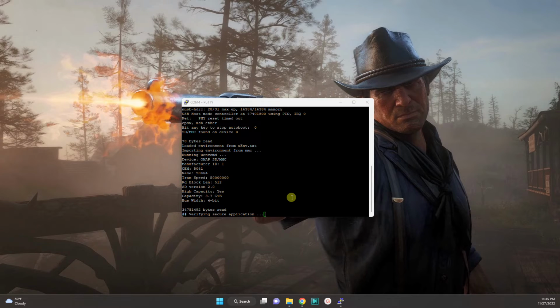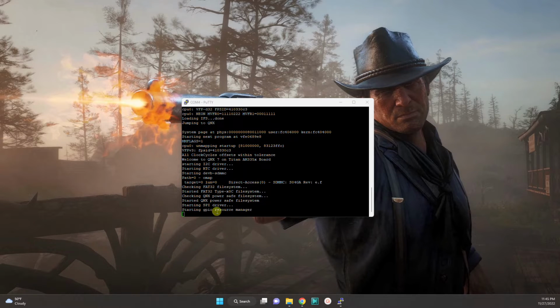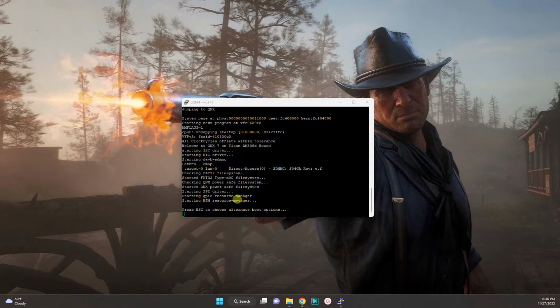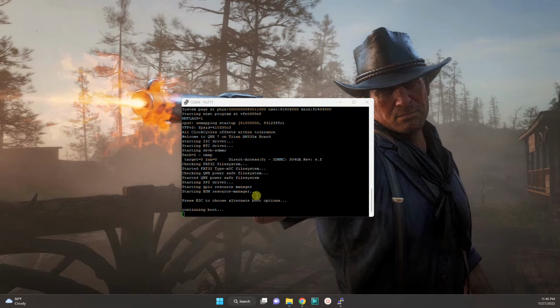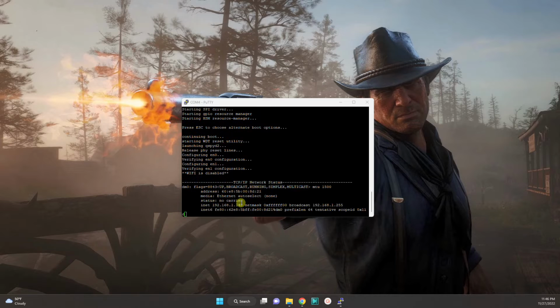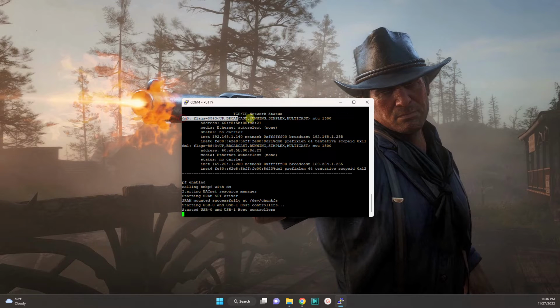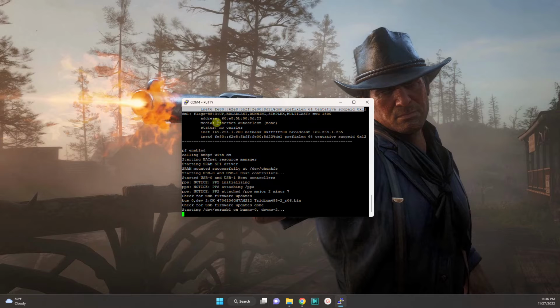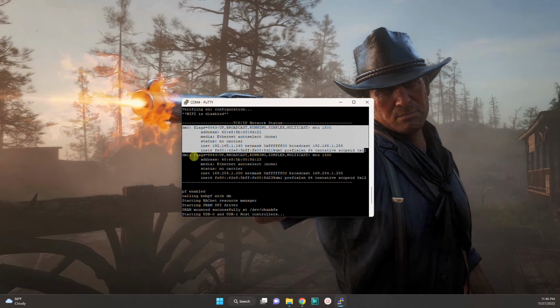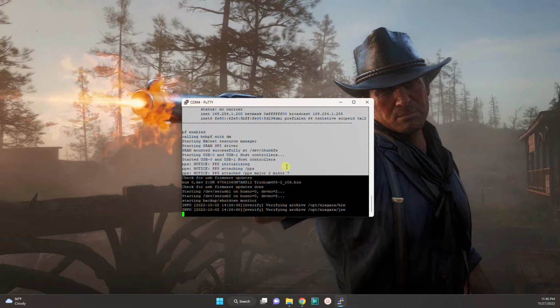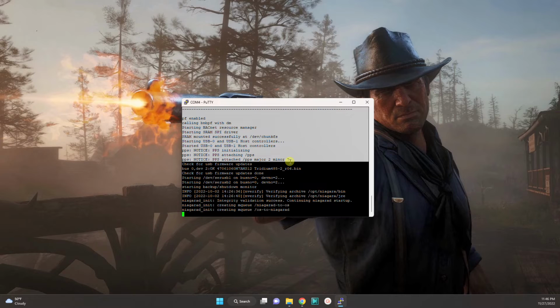What we are looking for is, once the application starts booting, you'll see TCP/IP parameters, and we should see DM0 and DM1 parameters there. DM0 is the primary port, and DM1 is the secondary port. So let's give it some time for the JACE to boot, and I'll pause the screen. Okay, so you can see the TCP/IP network statistics here. DM0 is our primary port, which you can see has an application and has an IP address, and DM1 has another IP address which you can see right now.